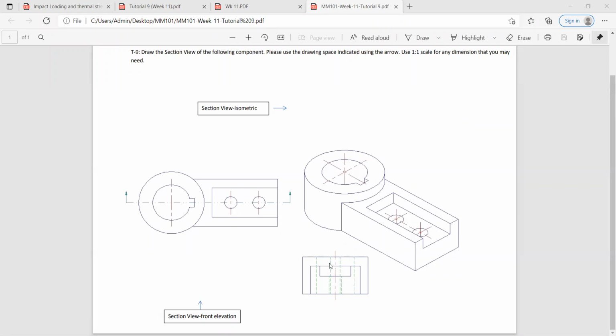Right, so this is the sectional cut plane. This dotted line shows where the sectional plane is. And we are looking in the direction of the arrows. So the arrows are pointing this direction. We're looking in this direction of the object, so looking at the front elevation. And the cut will be parallel to that front elevation, and it will project perpendicular to your eyesight or your viewing plane.